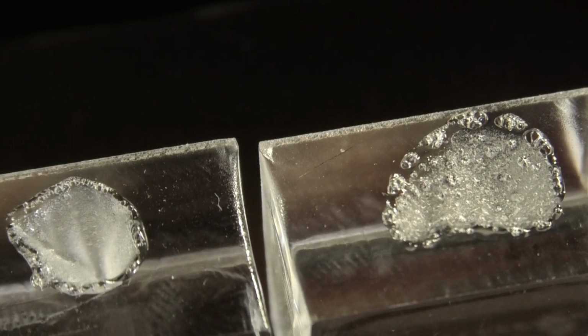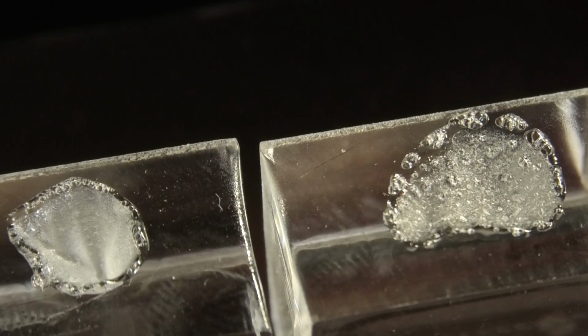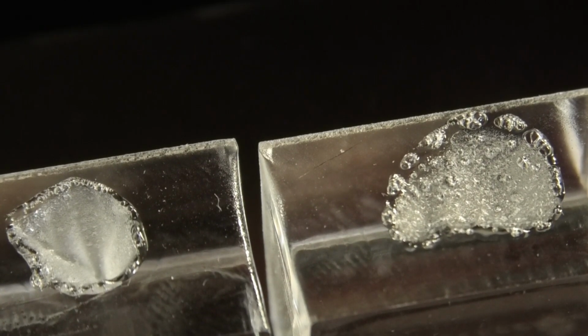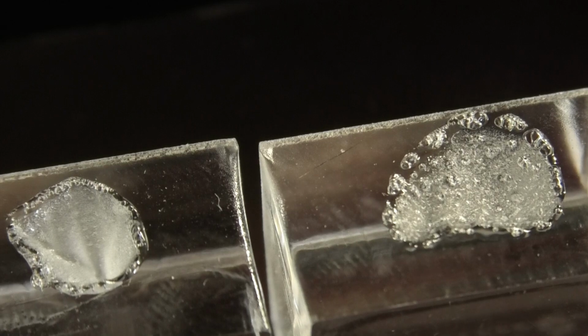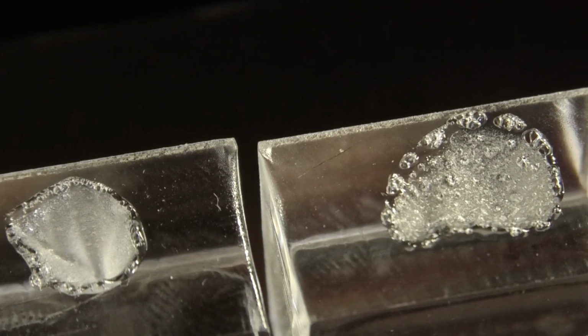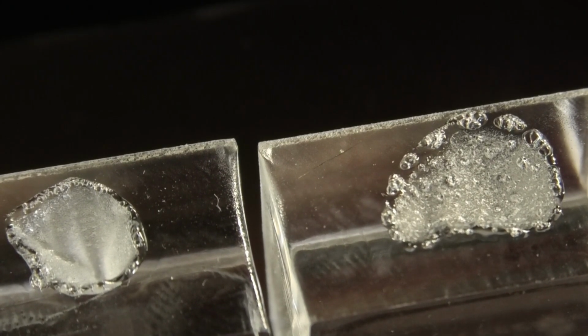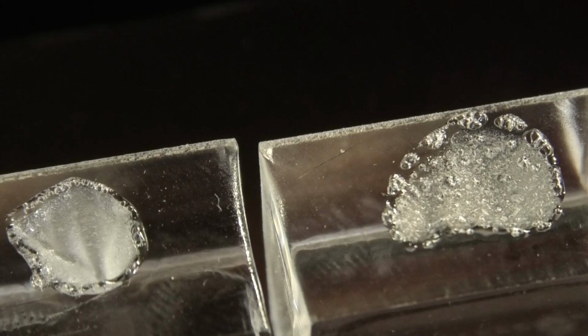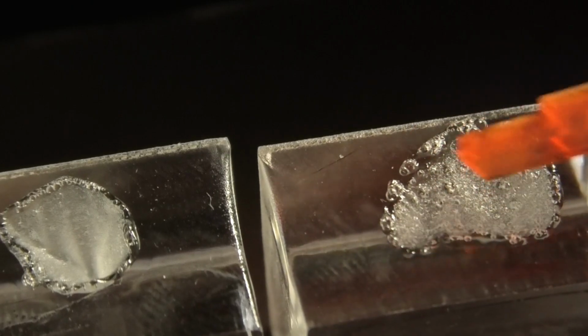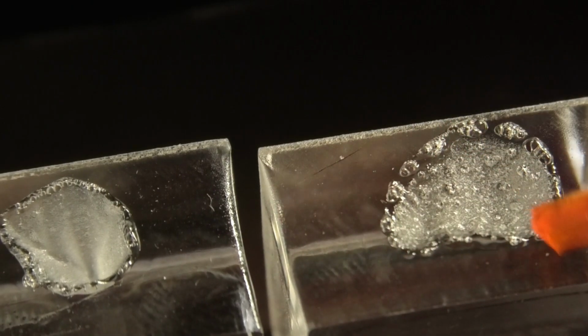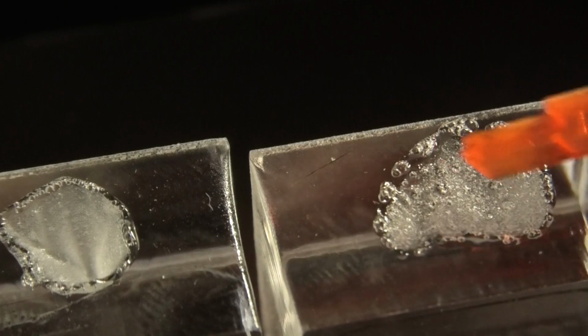So acrylic is a very interesting material, which is why I use it for doing this test work, because at 160 degrees C it turns to liquid, just in the same way that ice turns to water at 0 or 1 degree C. It's very similar to water in that characteristic, because when you heat this stuff up to 200 degrees C, it does exactly the same as heating water to 100 degrees C. It boils and evaporates.